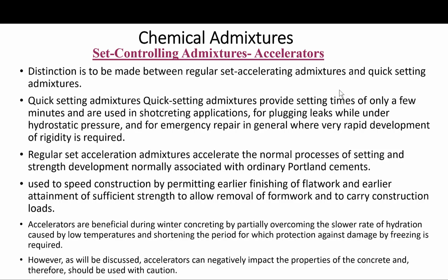Quick setting admixtures basically provide setting times of only a few minutes and are used in shotcreting applications or for plugging leaks while under hydrostatic pressure, and for emergency repairs, in general, where rapid development of rigidity is required. So that's the difference between the normal set accelerator and the quick setting.